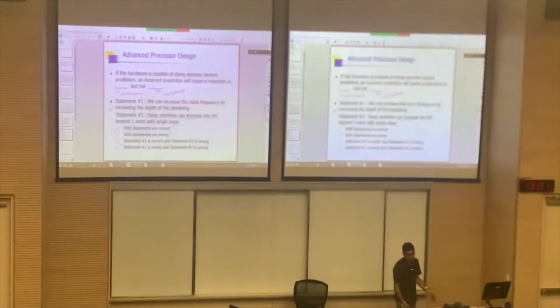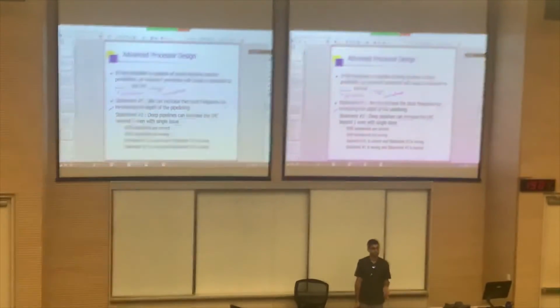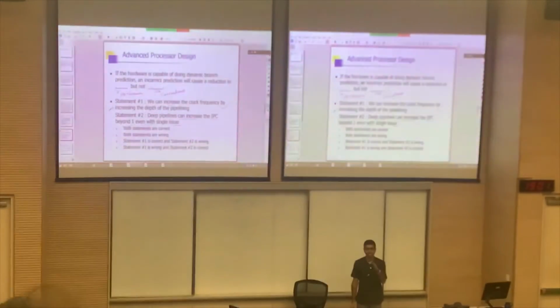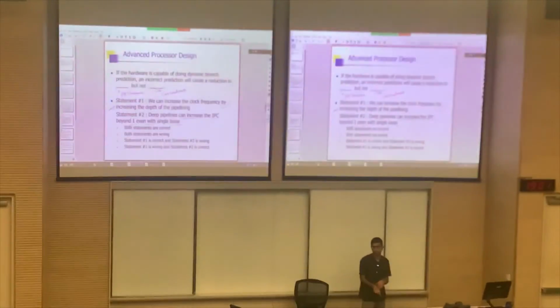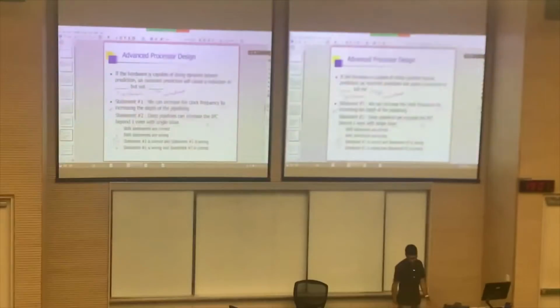But for a pipeline processor, practical IPC will be less than 1. Because in practice there will be some cycles during which no instruction completes. Right? So practically it will be less than 1. So this is not true. Okay, so statement 1 is correct and 2 is wrong.